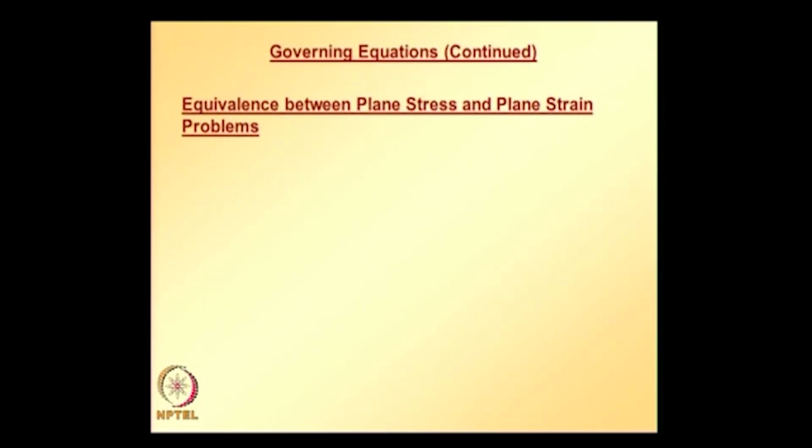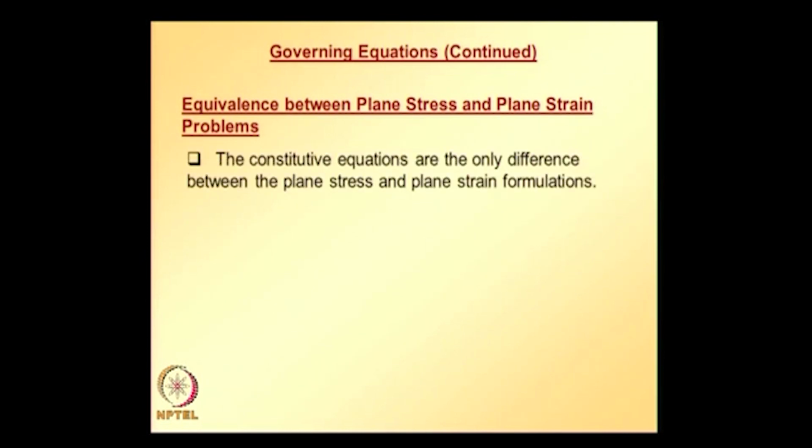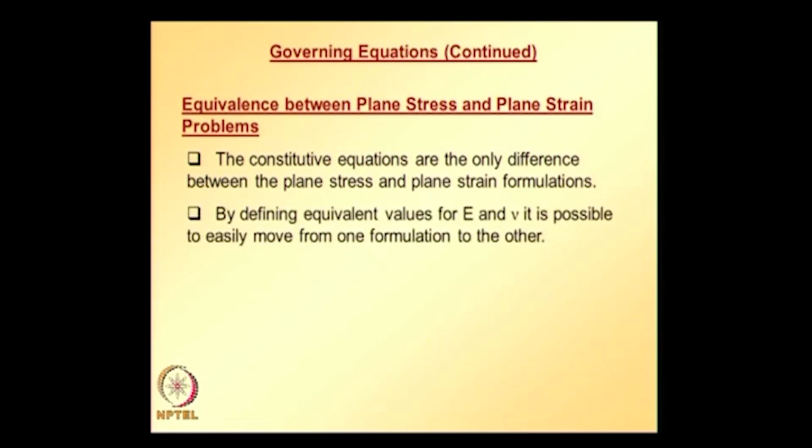The constitutive equations are the only difference between plane stress and plane strain formulations. By defining equivalent values of Young's modulus and Poisson's ratio, it is possible to easily move from one formulation to the other.